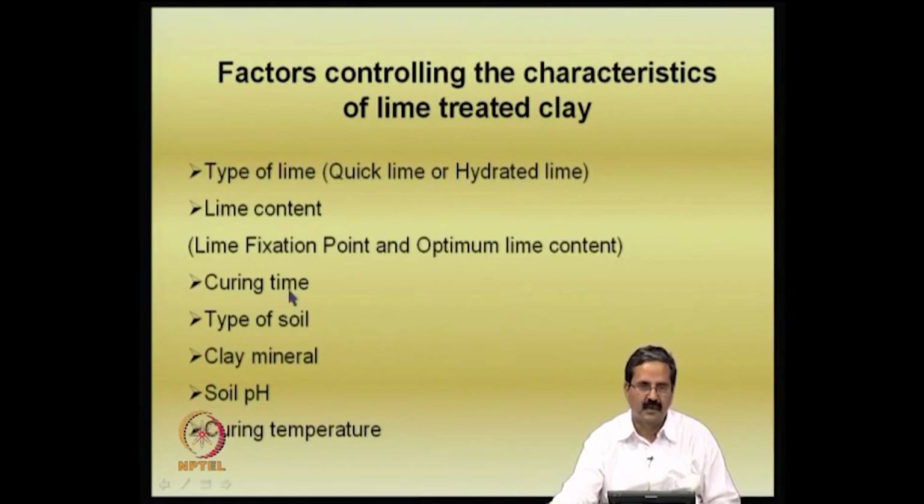So, for example, it can be different: 1 day, second day, 1 week, 1 month, 1 year. People have observed that these properties will increase with time because of the formation of cementitious compounds. So, the behavior of the lime treated clay is a function of curing time as well.